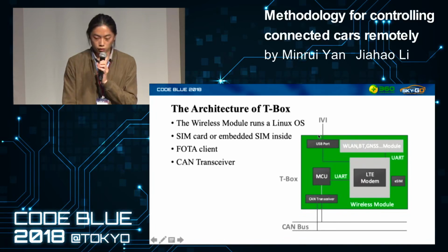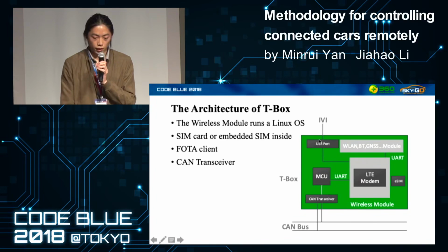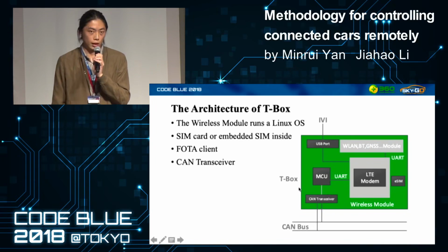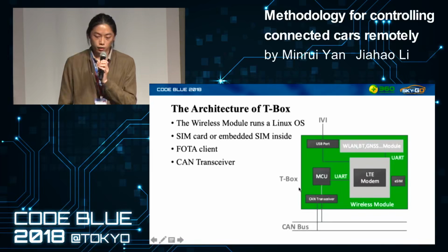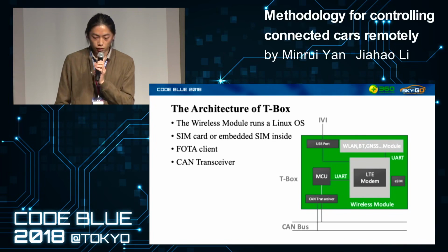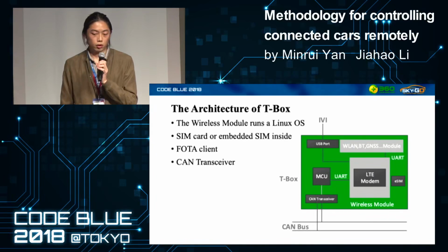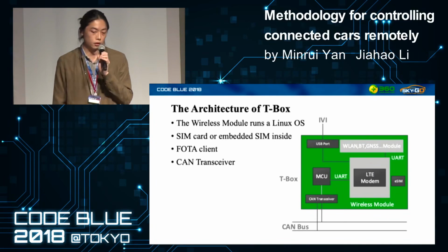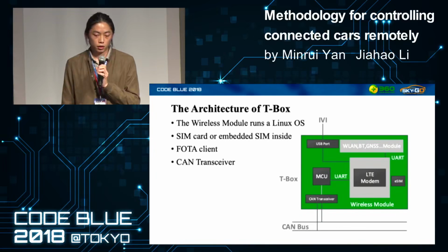This is the USB port. And the MCU sends CAN messages by a CAN transceiver. Then the FOTA program runs on the SoC, and it's able to upgrade the MCU and RVI. As an embedded device, it also has some debug ports for flashing firmware and on-chip debugging. And it always has a system such as Linux, Lite, or Android. You can find it in a flash memory chip.